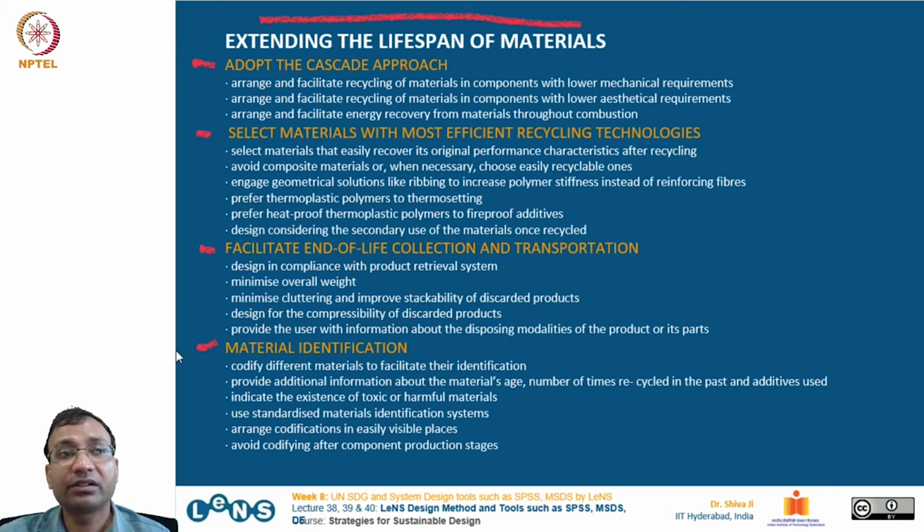Engage geometrical solutions like ribbing to increase polymer stiffness instead of reinforcing fiber. Prefer thermoplastic polymers to thermosetting. Prefer heat-proof thermoplastic polymers to fireproof additives. Design considering the secondary use of the materials once recycled.